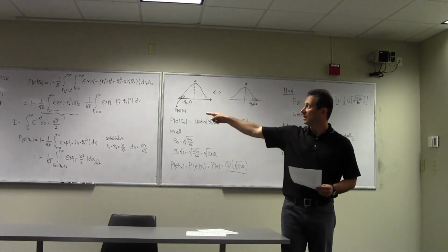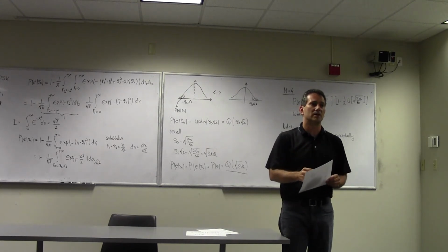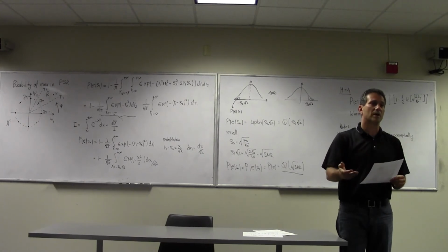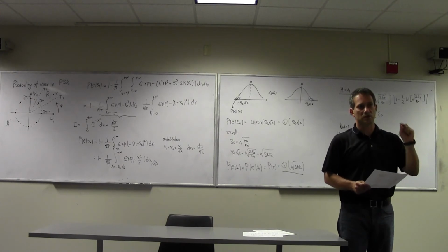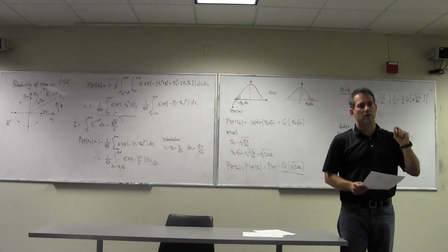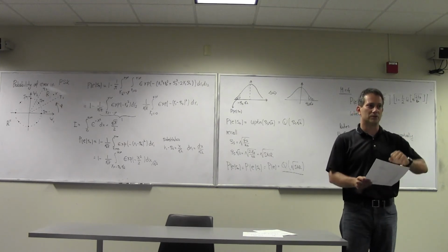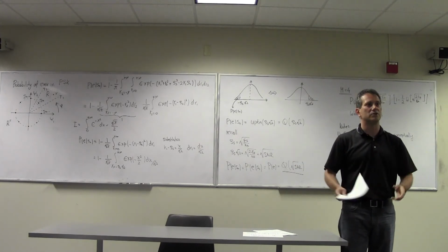One is this view in a constellation diagram, which says as you have more symbols in a circle, they're closer to one another. Given the same noise, or signal-to-noise ratio, then it becomes more likely to make an error. But it's even more fundamentally clear to us using Shannon's capacity formula. Because when you go to M equal 32, you're packing more bits per symbol. So your bits per hertz is larger, therefore, because you're getting a larger capacity, your signal-to-noise ratio needs to be larger.